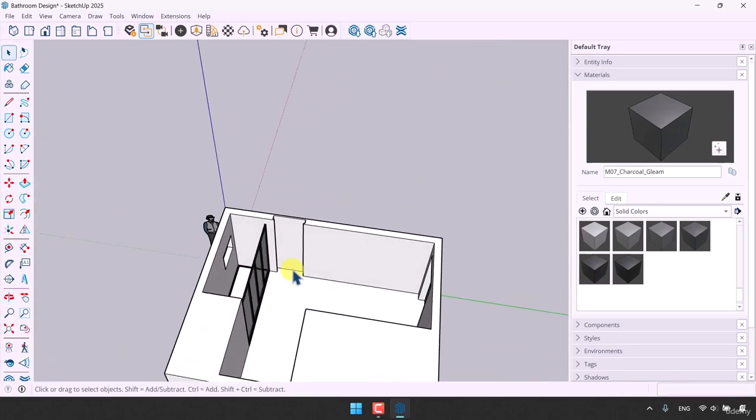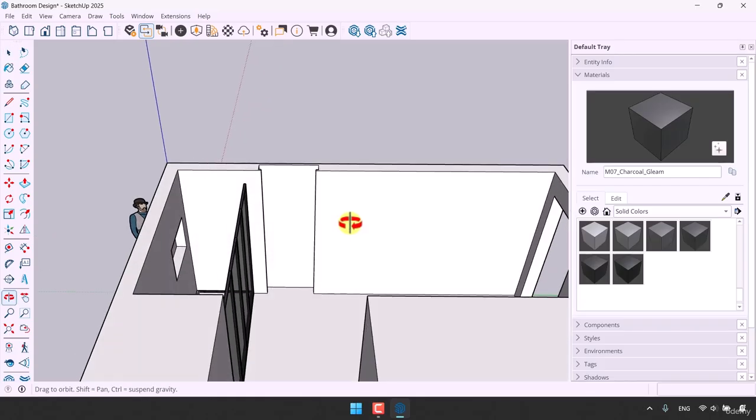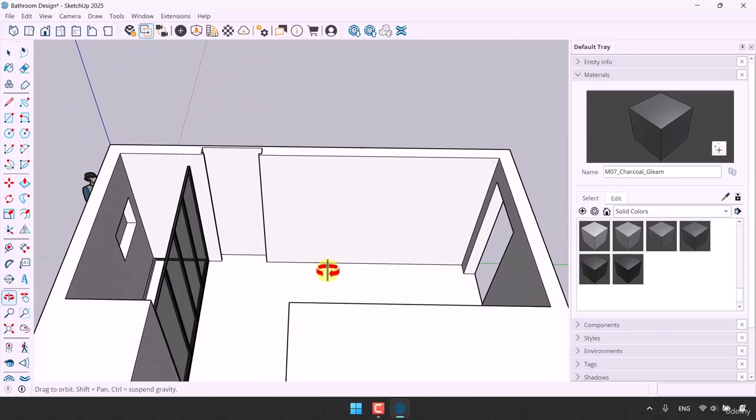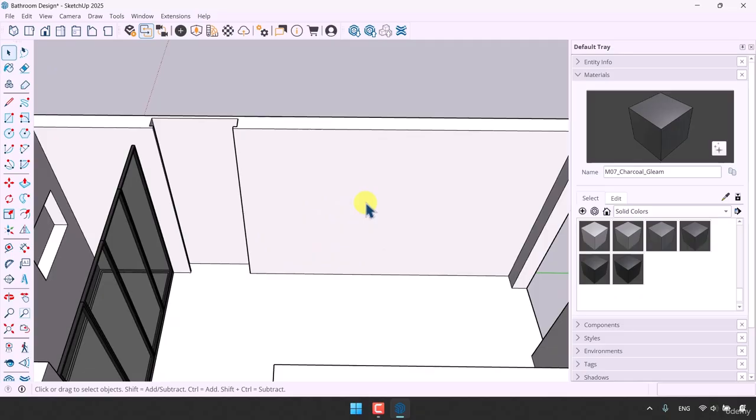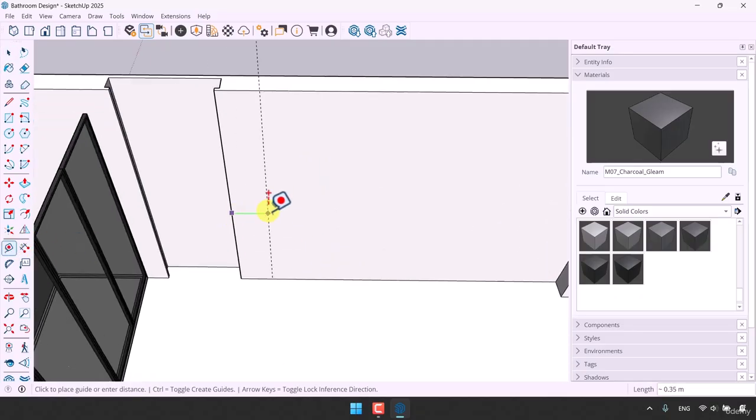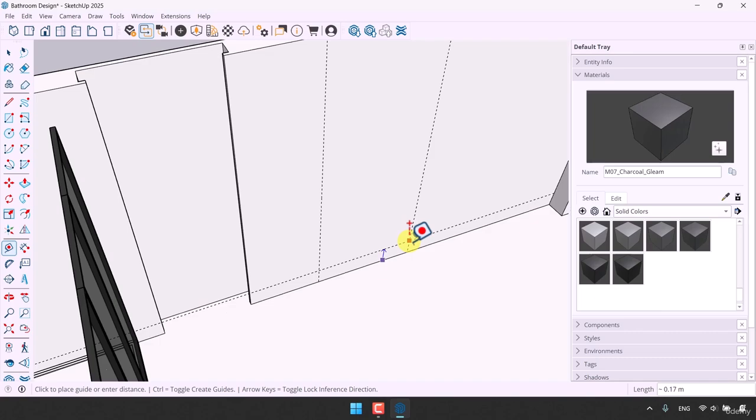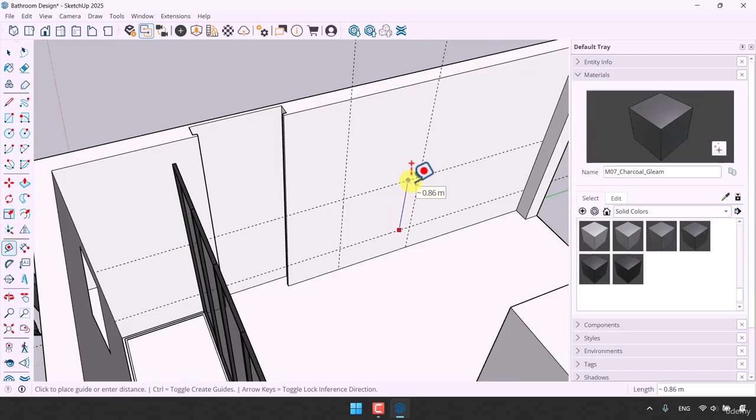And at the end, I want to show you what I want to add for this place. So this part is done for me. Now in this part, I want to create some sink for washing hands. So I'm going to generate some place for it. I'm going to add some type of architectural dimension about 70 centimeter distance for it. And we imagine a 1 meter console is enough for it. So from the downside, I want to space it about 40 centimeter. And the height of this must be standard. So totally 1 meter is enough.